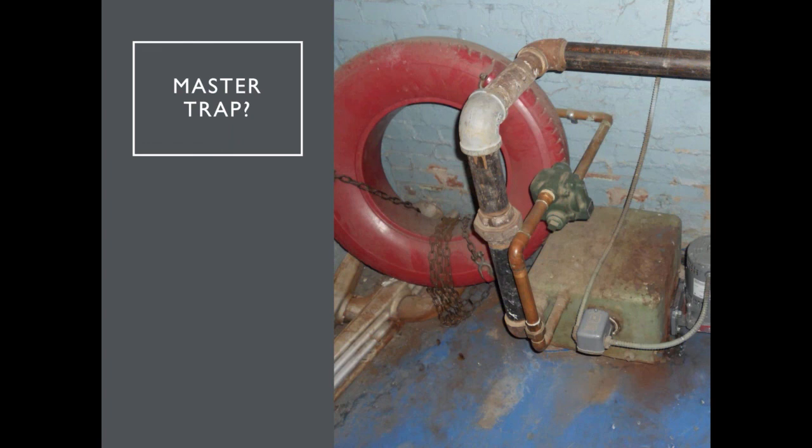Because what you're going to need on a steam boiler is usually 3 different things. You're going to need an oxygen scavenger. You're going to need something that's going to help with the carbonic acid that forms, and you're going to need something that's going to stop the scale. So I don't like to take that responsibility on myself. I like to let them use a water treatment company. That way they take the responsibility for it.